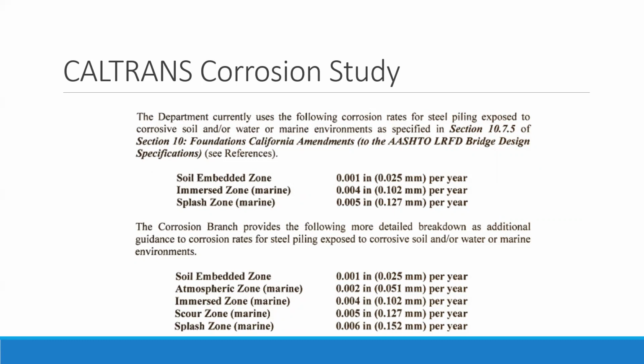So as part of our design process, we first look at the wall thickness required to achieve the structural capacity or structural requirements of the structure, and then add in additional wall thickness to be utilized as sacrificial steel to achieve the desired design life, whether that be 60 years, 70 years, 80 years, 100 years.